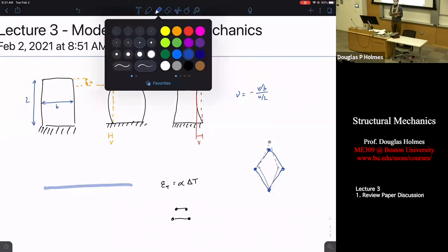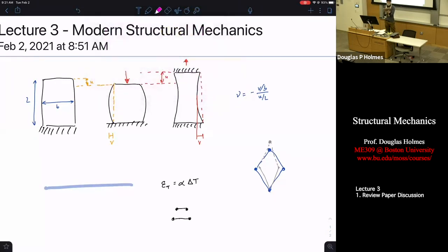People realized really long ago that if you take two metals that are different and you glue them together, then you have a problem, because now the blue material might have a material property so when you heat it up it expands a ton, and the pink material might have a property where you heat it up and it expands a little bit. Just a material property. It depends a little bit on the arrangement of the atoms and how easy it is for them to get excited when you turn up the temperature.